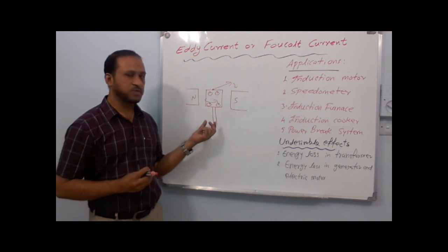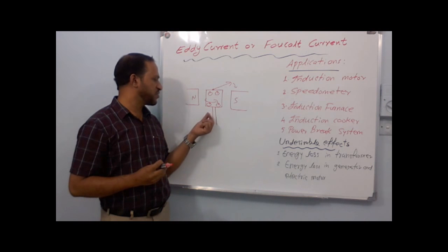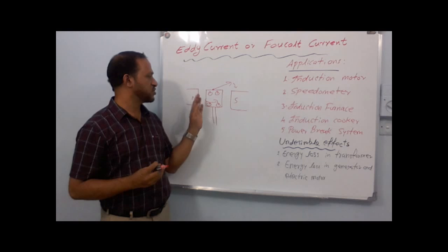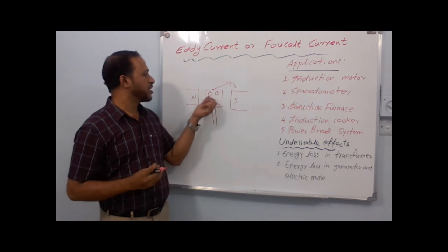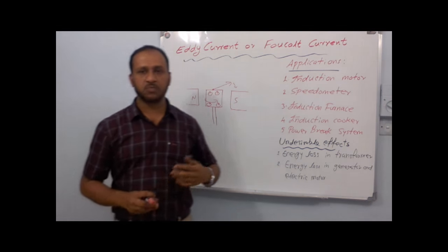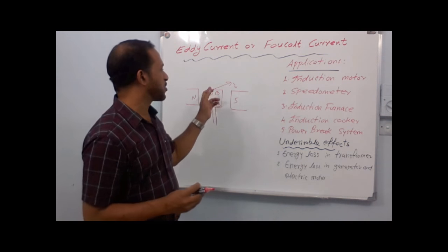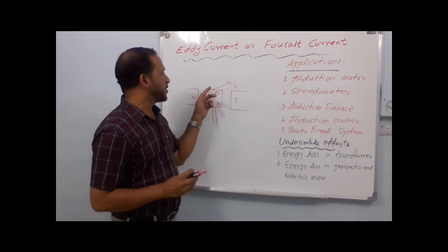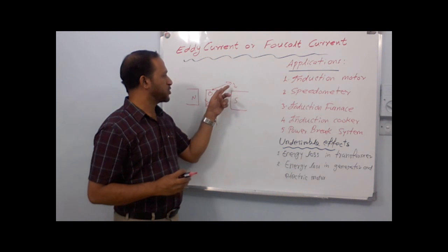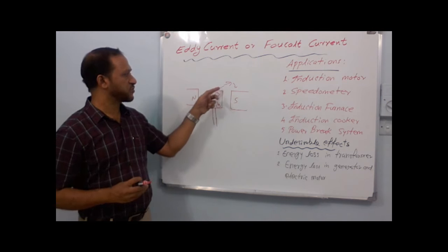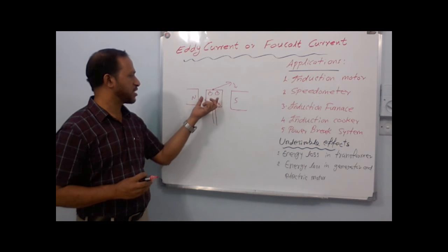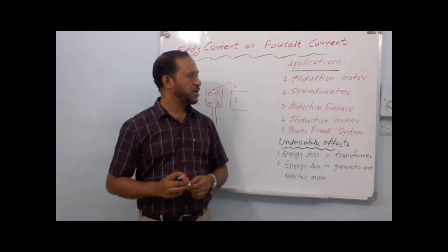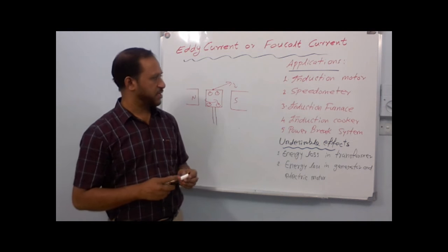So if the vehicle is moving with more speed, the cable will be spinning with more speed, so the aluminum drum also rotates very fast. This means the variation or change in magnetic field will be more, and more eddy current will be induced, so it will experience more force, more torque, so it will rotate more distance, more angle. So we can see that the speed of the vehicle can be proportionally obtained from the angle of rotation of the needle that is in turn connected to the aluminum drum. So the speedometer of a vehicle is also working according to the principle of electromagnetic induction.